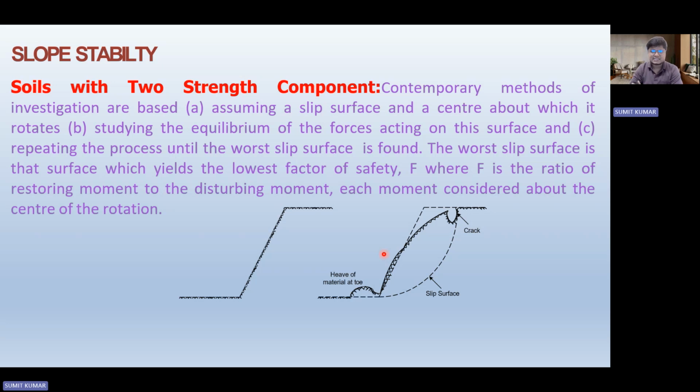Now, when the worst slip surface is identified, the lowest factor of safety is stated, and that is going to be the critical surface through which failure takes place in adverse conditions. On the basis of that, we have identified the critical failure surface. We already have the properties of the specific site, through which we have calculated the safety factor. Hence, the factor of safety could be stated.